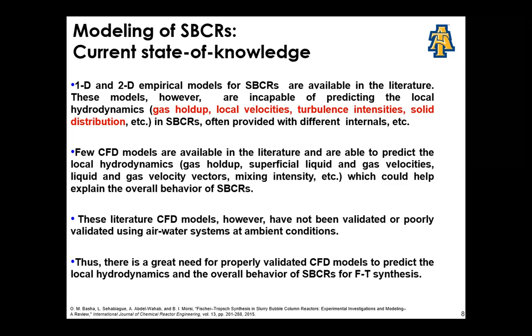Few computational fluid dynamics models are able to predict our local hydrodynamics, which could help explain the overall behavior of slurry bubble column reactors. But the problem is our CFD models haven't been properly validated using air-water systems at ambient condition. Thus, there's a great need to develop more representative understanding of local phenomena in our slurry bubble column reactors.